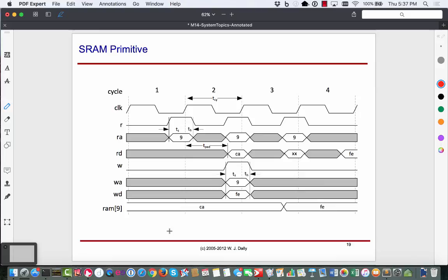So you'll find logic blobs with registers and stuff like that, and SRAM all on the same chip. Flash memory again requires a separate kind of process. Again, they are separate chips. You cannot have them on the same die. But what people do is that they stack dies in 3 dimensions. So they may create a DRAM and a processor and then stack them up in a 3D structure. From the outside, it may look like a single computer chip, but inside there are multiple stacked dies.